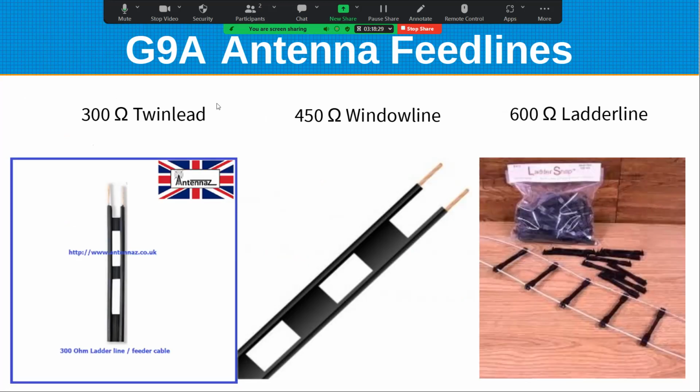Here's what they look like. This over here, this ladder line is commercial, with their little dog bone things. But there's nothing magic about it. It's just the size of the wire and how far apart it is, and the fact that that's a good insulator. Also, sometimes if you just allow a little bit of a twist in your parallel line, that makes it a little bit quieter.